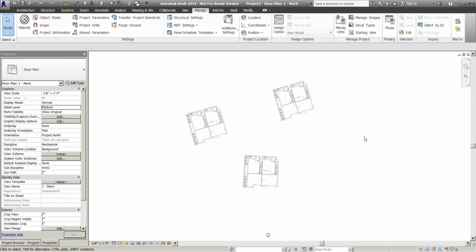Okay, and actually, this is a good point in here. Brandon has a question. How does the different locations affect the project north of the linked file? And I think this is a good example where we can see where I believe my site plan I had rotated as a different true north facing, and that's why we're getting this particular project north versus true north within here.